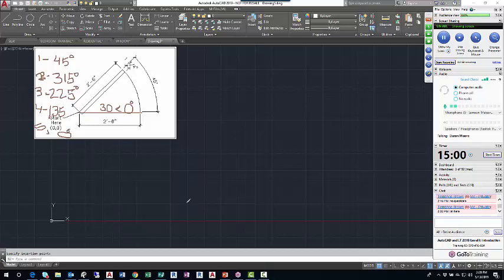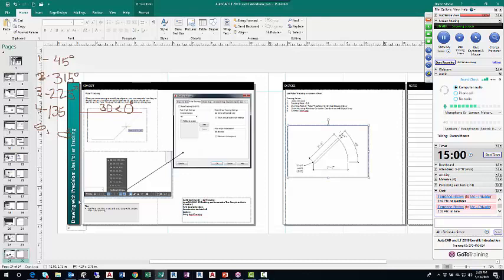Okay, so let me do this once, and then I'll undo it. We can do this together. I might pass through my little helper image here. Hopefully not. But the graphic on page 24 shows polar tracking. We're going to use polar tracking instead of ortho. Ortho forces us to draw at horizontals and verticals, or at 90-degree incremental angles.